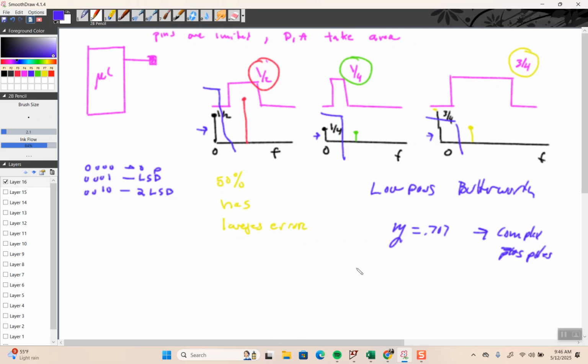Right? So I get my minus 40 dB per decade roll off. There is no peaking in the Bode plot, but in the step response there is. All right. So by designing a pulse width modulated DAC, right, you're getting the Fourier, you're getting the filter design, and you're kind of tying the whole course together.